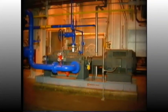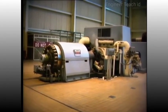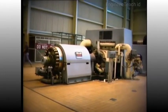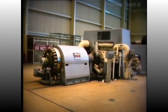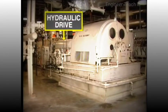The feedwater pump may be driven by an electric motor or a steam turbine. The steam turbine has the obvious advantage of variable speed control, which can be used to adjust the quantity of water being supplied to the boiler. Of course, the same result can be achieved by applying a variable speed hydraulic drive between an electric motor and the pump. The ability to control the quantity of water being pumped into the boiler is vital for safe boiler operation, and the control system must be able to respond rapidly to changes in water level in the boiler caused by variation in turbine load.